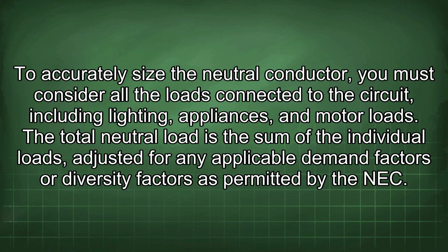To accurately size the neutral conductor, you must consider all the loads connected to the circuit, including lighting, appliances, and motor loads. The total neutral load is the sum of the individual loads adjusted for any applicable demand factors or diversity factors as permitted by the NEC.